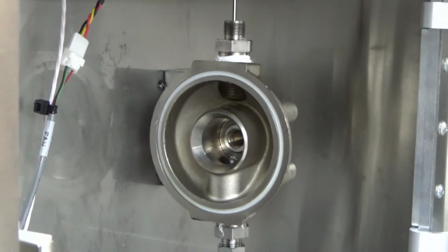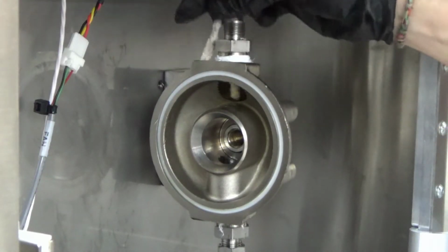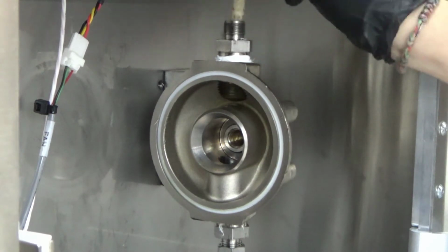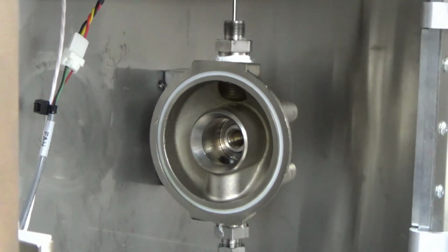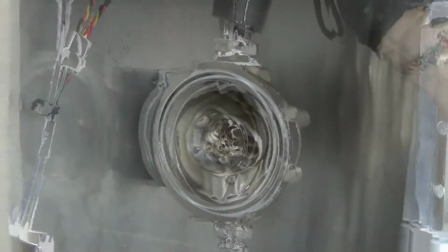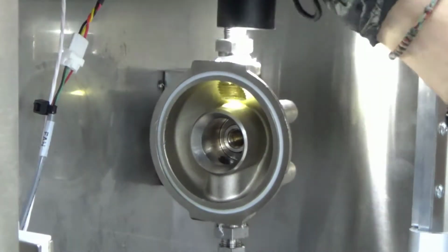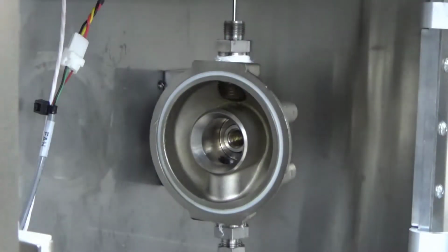Now, we will check the inlet of the exhaust filter mounting block. This is the most common location of wax buildup that causes clogs. If necessary, use a supplied pipe cleaner to clear the channel of buildup. You can determine whether this channel is unclogged by shining a light through the top of the filter fitting.